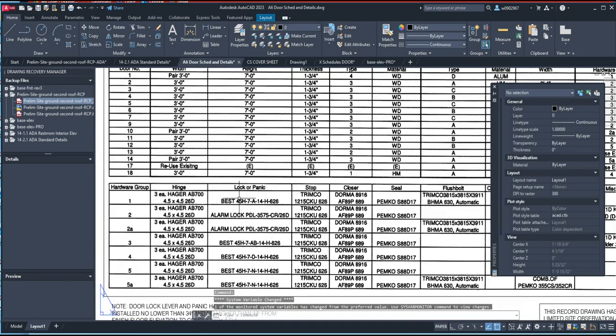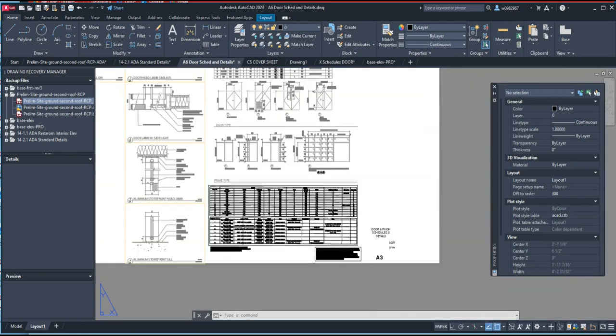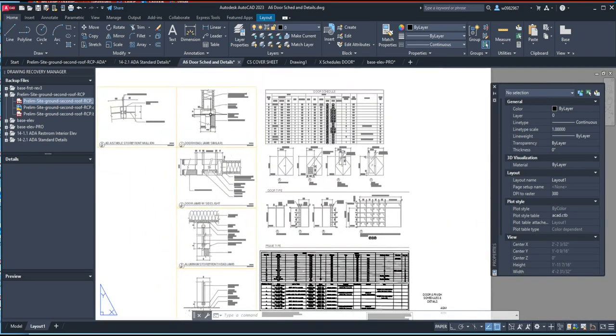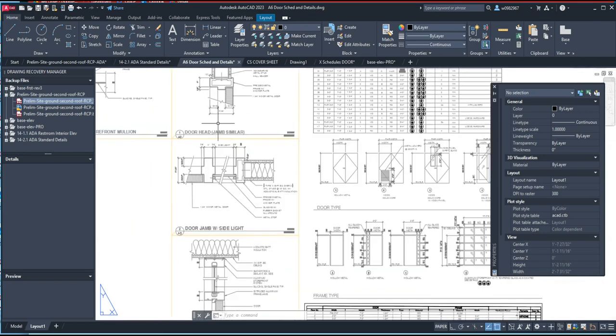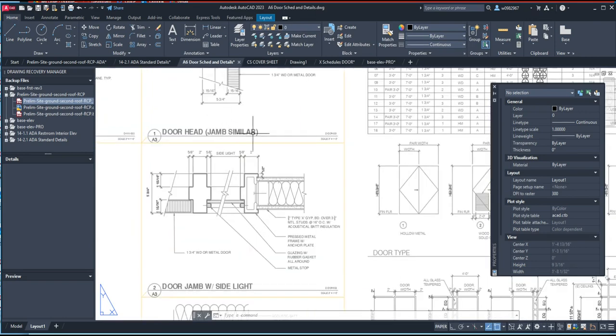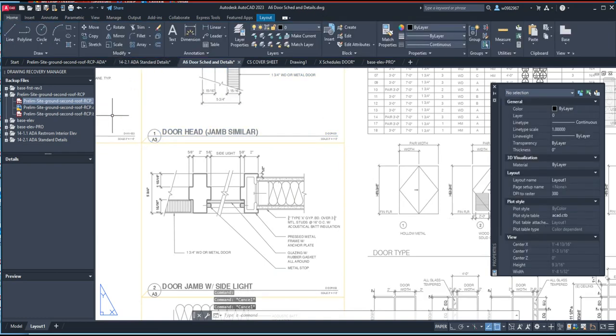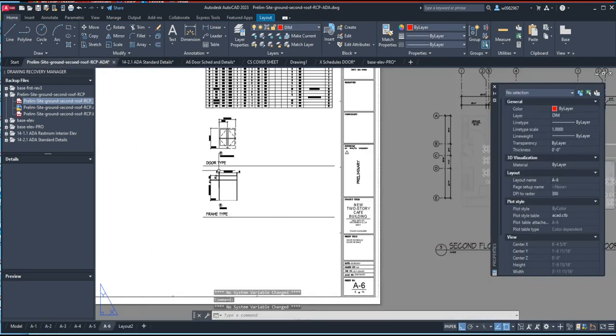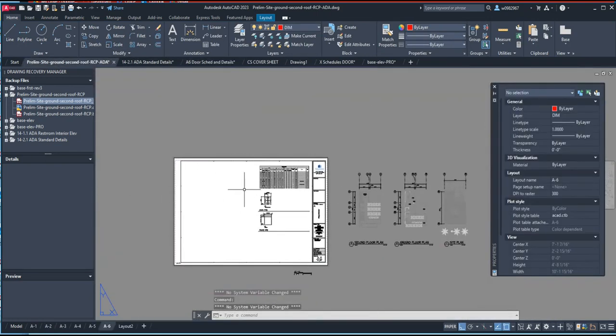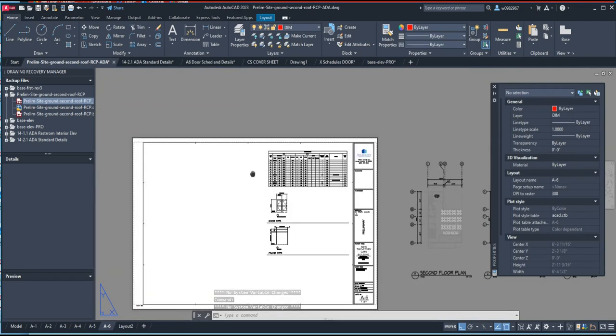That's this one. This is a picture that was inserted, so you can't copy this, and you need to create your own table, and we've created tables before. Okay, and then this one, these are schedules, the details. This one is called a door 001. So what we can do is we can go back here, and we're going to put the details on the left side. Okay, put the details on the left side.